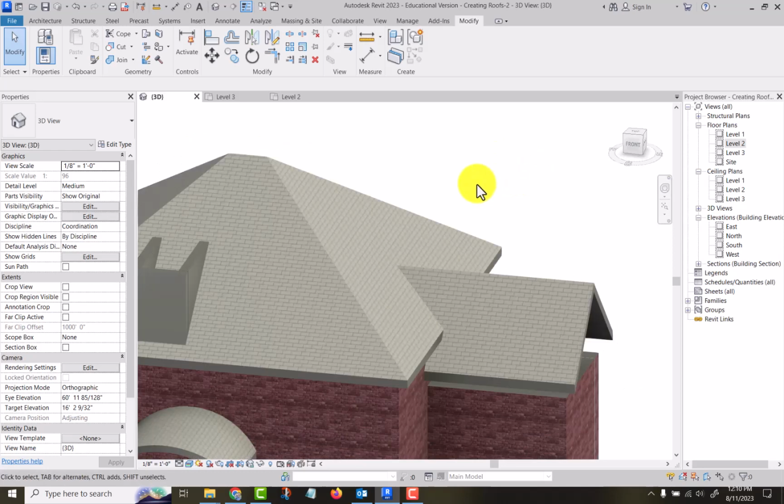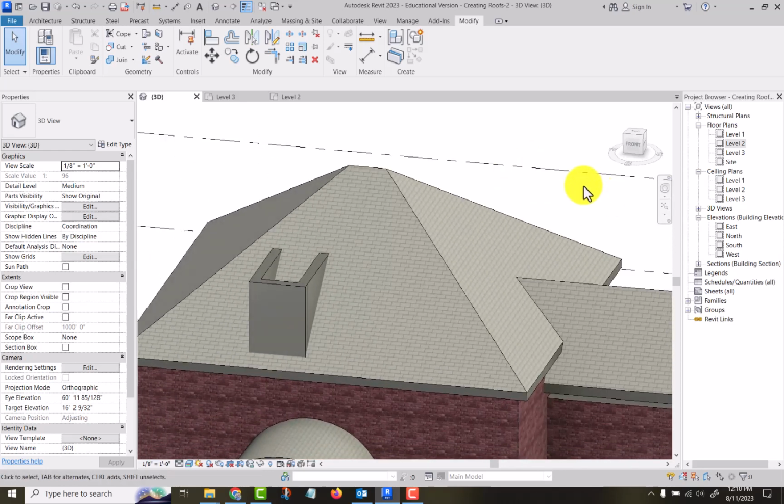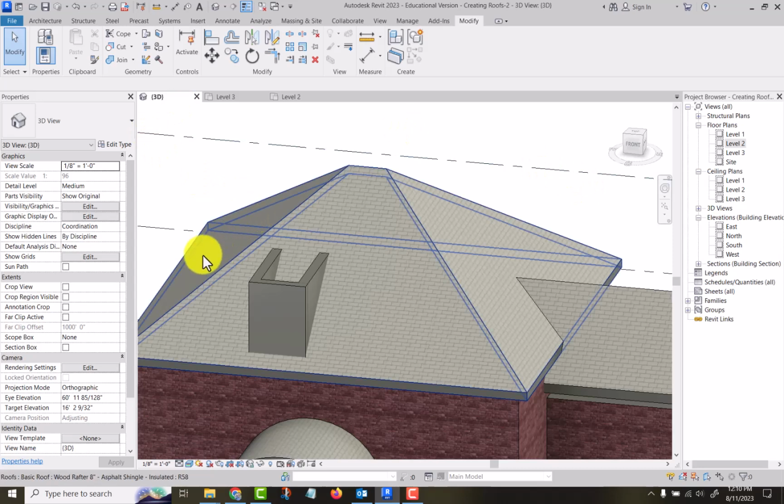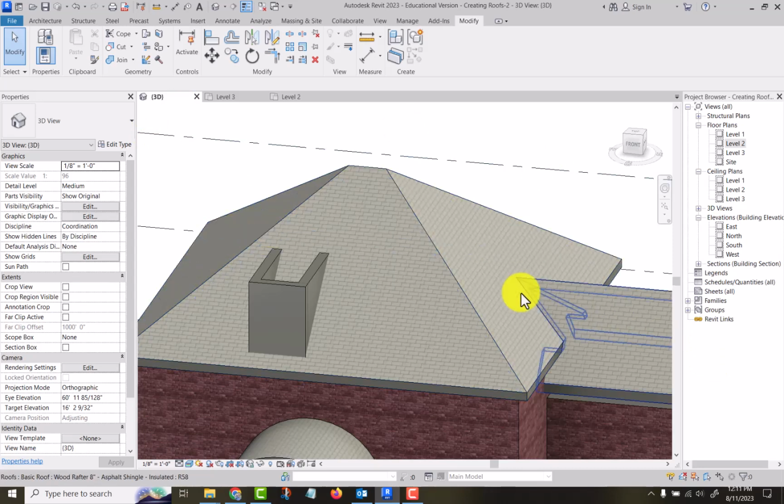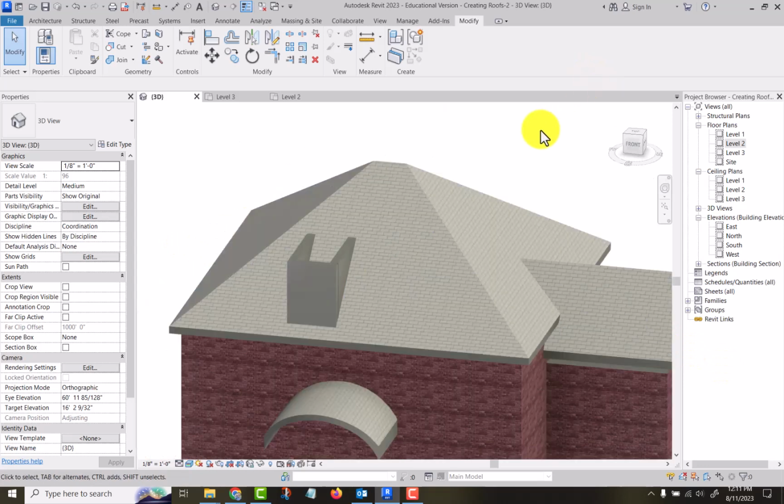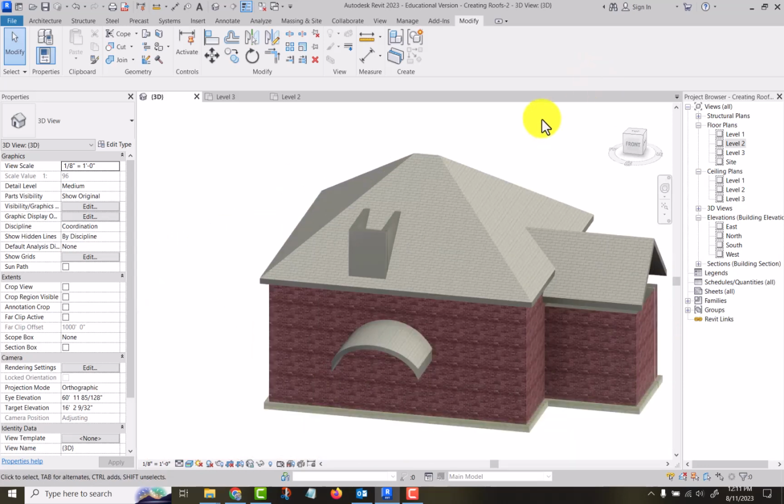And you can see it moves the roof over, joins those things together so materials look right and all that kind of stuff. Now you've got to be careful with this because if I had messed up and picked this surface plane, it would have extended that roof all the way through to this plane. Okay, so depending upon the shape of your building, sometimes you'll have to draw a roof and then extend it out.